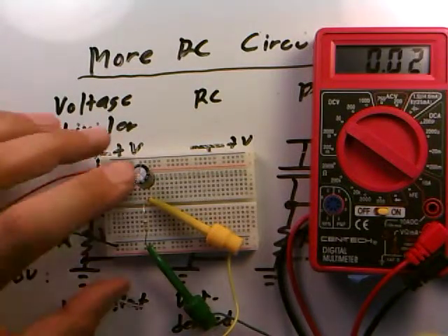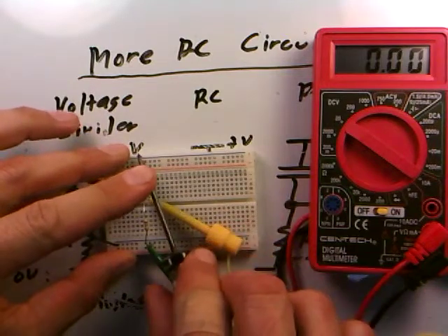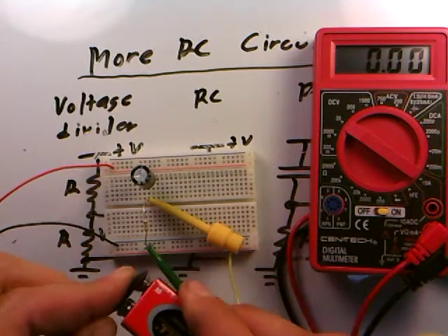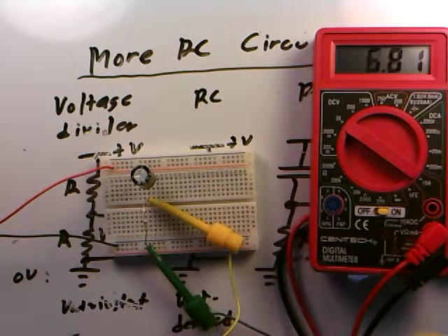So let's take the battery out again, short out the leads of the capacitor and run it again. So here we go. 3, 2, 1, and go. High. Went up to about 7.5 volts, and now it's slowly coming down. So we're seeing a nice asymmetry, if you will, between this circuit and the last one. Seems like when the capacitor was in the bottom, the voltage rose. When the capacitor was in the top, the voltage fell.